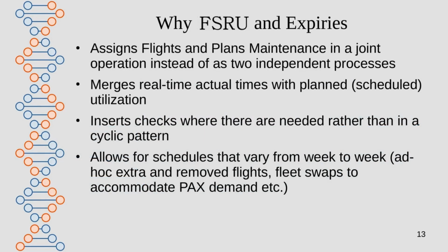One of the important reasons for planning maintenance against an actual schedule is that flights do not conform to cyclic patterns despite arguments to the contrary. Extra flights are added for special functions and holidays. Flights are removed or downsized during periods of low demand. And flights are adjusted at the starts and ends of seasons to align with adjacent seasons. When you add those variations together, you find that utilization patterns change all the time. Ideally, they are